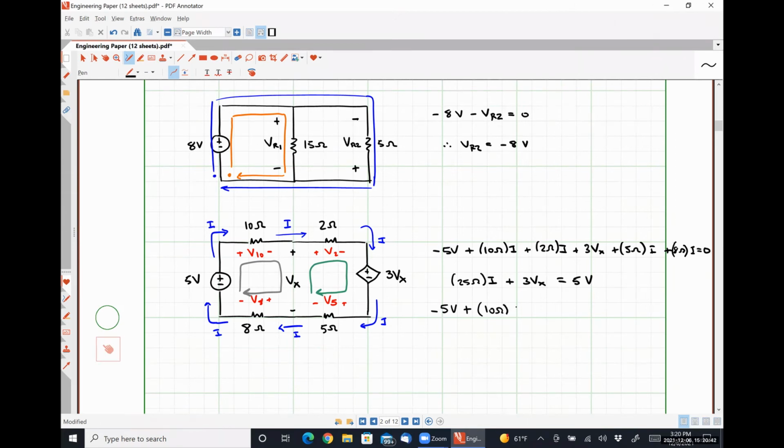It'll be 10 ohms times I, okay. And so now we're going across that Vx in the middle. So we see the positive polarity terminal first, so it's just gonna look like plus Vx. Because it's a voltage drop, we don't need to put a current or anything in there, right? Kirchhoff's voltage law is just adding up voltage drops. So plus Vx is perfectly okay. And now we're at this point right here, and we're headed to the left. What's next?